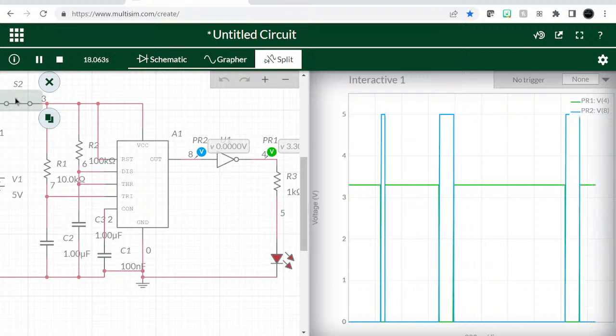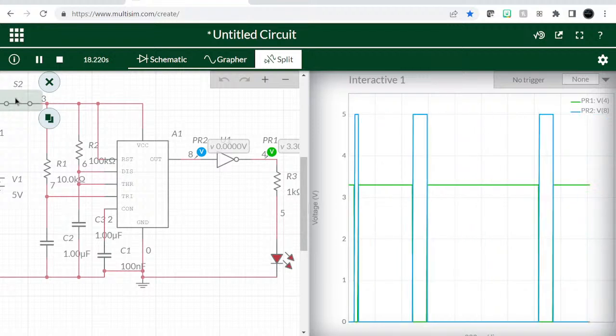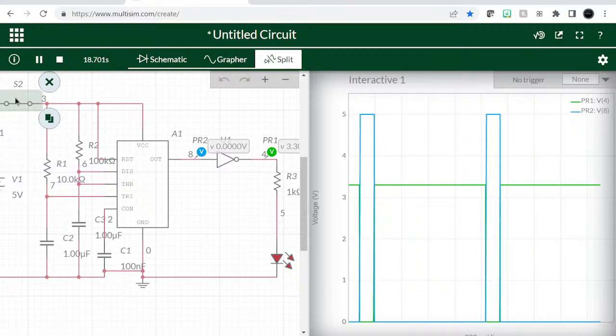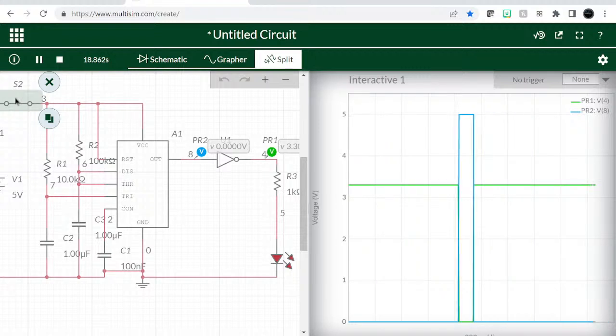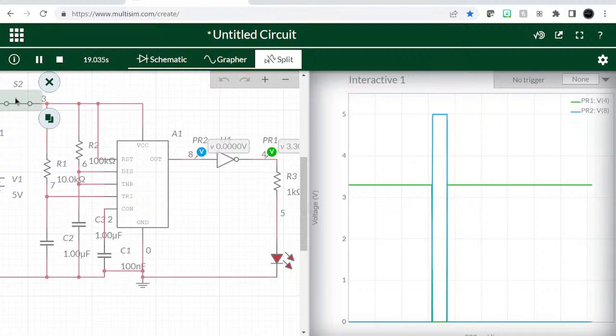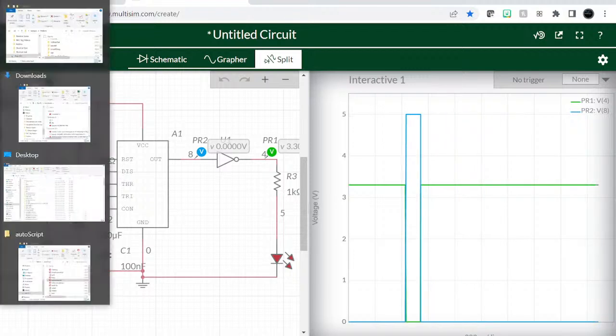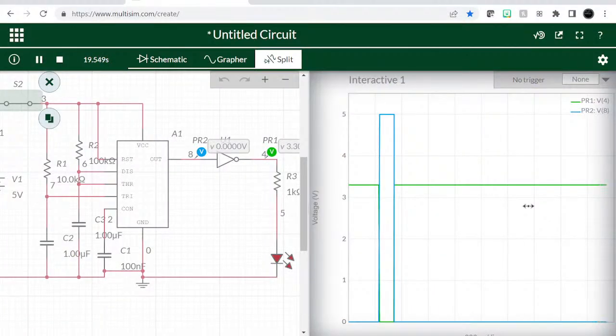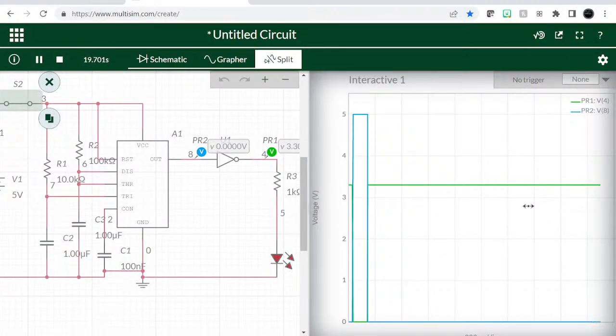And that period is my reset period. So it gives me a high, and then it drops. Right, so that high, you can use it to reset a high going reset system, but you can use an inverter to turn it around if you want to reset a low going system, a low voltage going system.